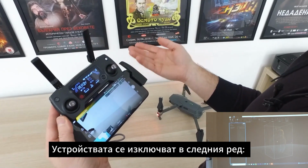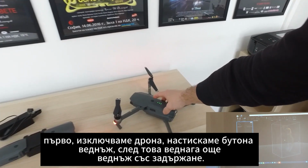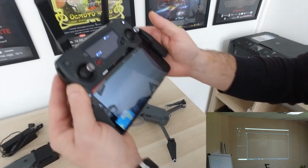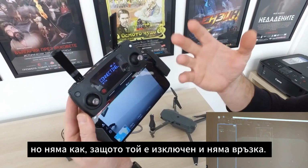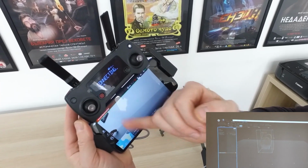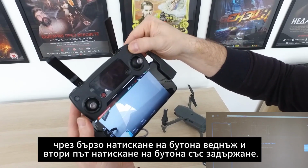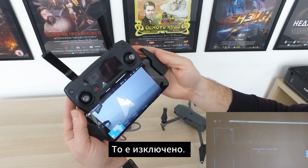The devices are switched off in the following order. First we turn off the drone: press the button once, then immediately a second time with hold. The display shows that it is trying to connect to the drone, but there is no connection because it is turned off. The remote is turned off in the same way, one time fast and the second time with hold. It shows a shutdown. The device is turned off.